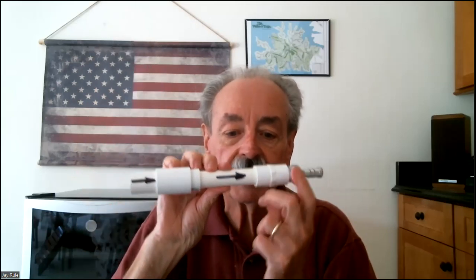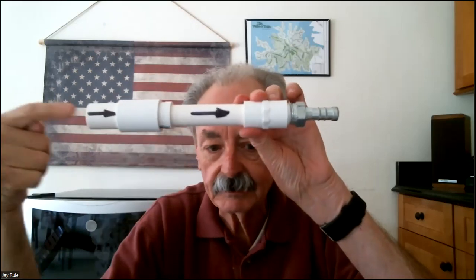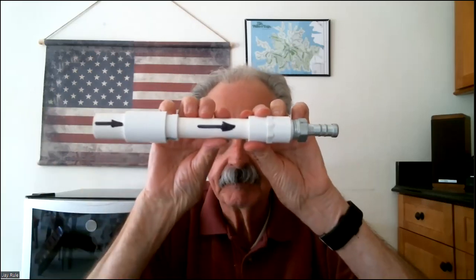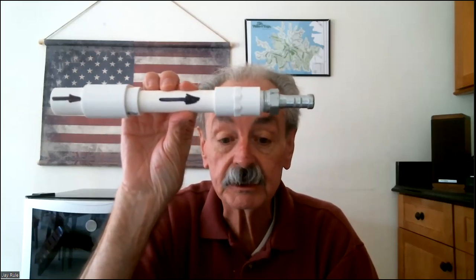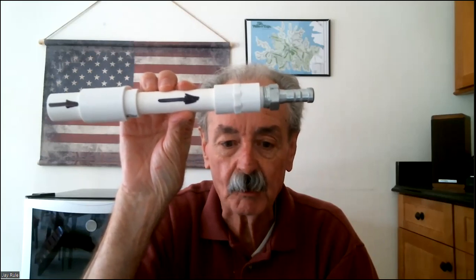If I get this set just right, you can see both the inlet area and the outlet area. If I can hold this still. So you see the inlet area is closest to you, big, and the outlet area, much, much smaller. So this is just a good example. And do you see how this would be a steady state, steady flow control volume? One inlet and one outlet. This equipment's neither getting fatter or skinnier. It's just sitting there with some flow going in and exactly the same flow going out. Homebrew nozzle.